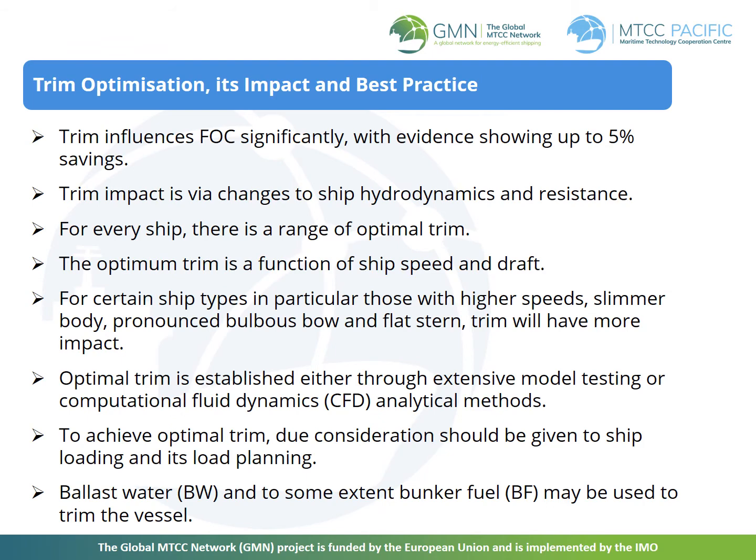Most ships are designed to carry designated amounts of cargo at a certain speed for particular amounts of fuel consumption. The same applies to ballast operations, whether loaded or unloaded. For such conditions, normally there exists a ship trim that minimizes the propulsion power and thus the main engine's fuel consumption. For any given draft, there's one optimum trim that gives minimum ship resistance.